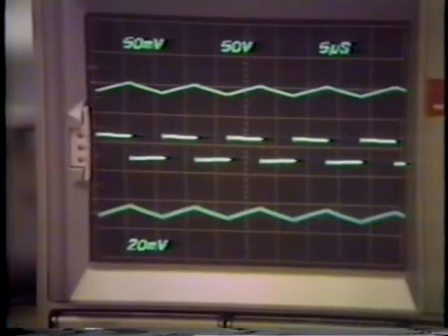Of course, that is because if you look now at the BH loop characteristic, the characteristic of flux linkages versus current is now contained to the smaller portion where it is still in a linear region, and therefore both flux linkages and current are linear waveforms.